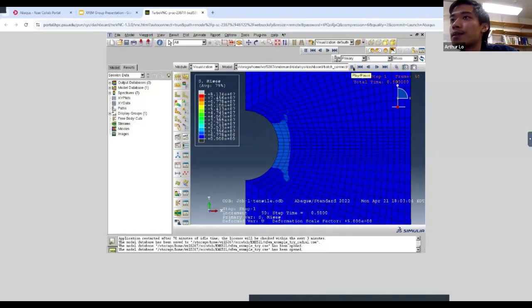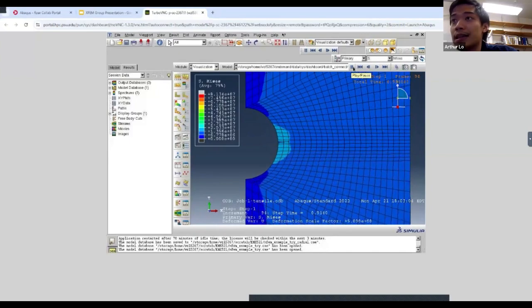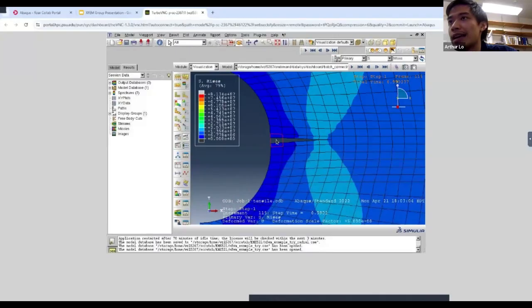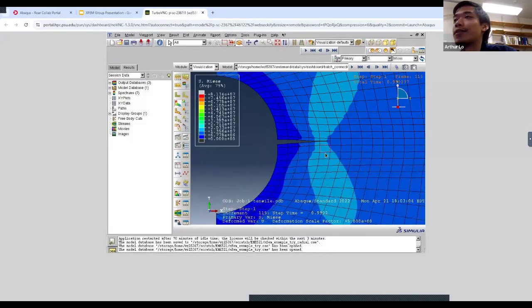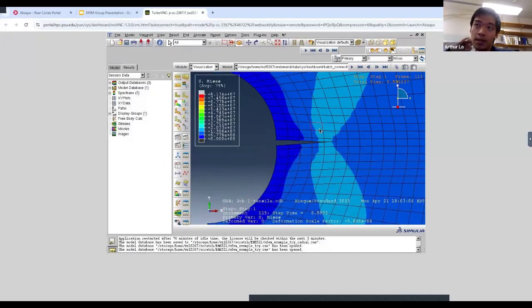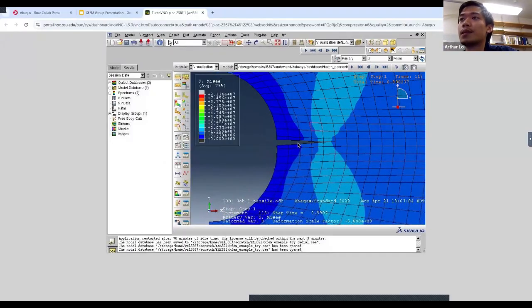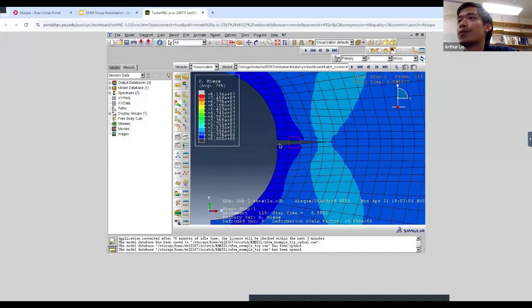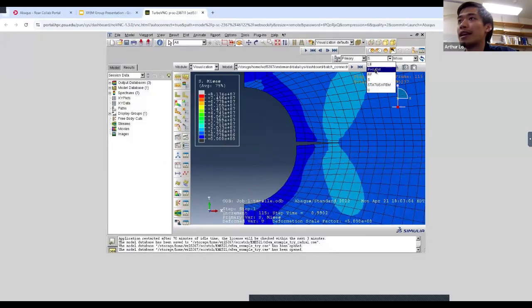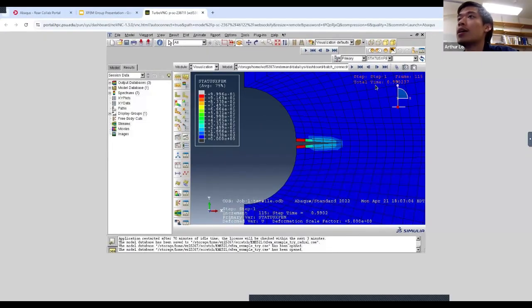So you notice that the crack is in between two elements, essentially, in between, in one element. Sorry, it's cutting through the element itself. So that is the power of the XFEM method. We don't have to refine the mesh around the crack in order to generate this model, or to account for the deformation. We can just cut it right through by relying on those enrichment functions.